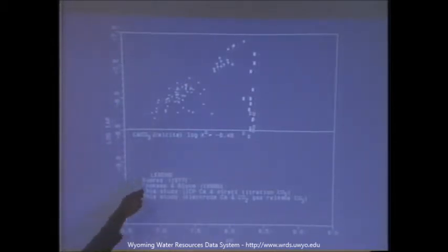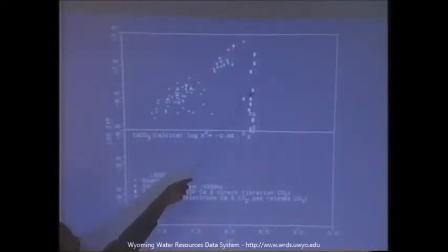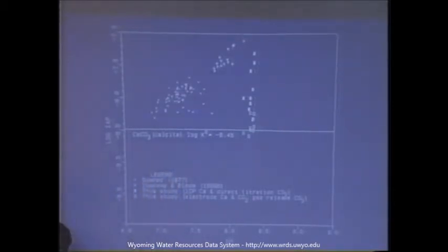Okay, these closed symbols were all measured with calcium by AA or ICP, and then direct titration of carbonate alkalinity. So these values, open and closed symbols, and all these are included with organics and inorganics, whereas the open symbols are just inorganic calcium and carbonate activities. So you can see these values suggesting equilibrium, whereas these are supersaturated.